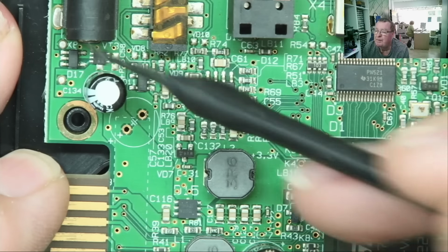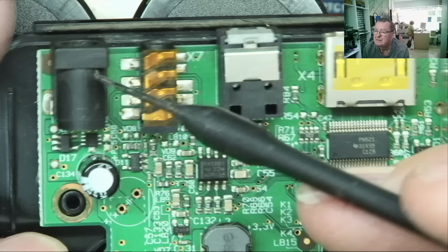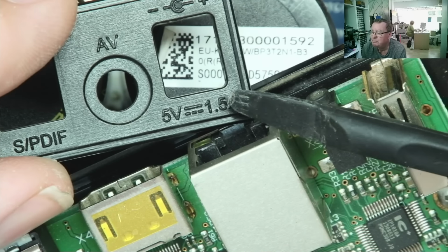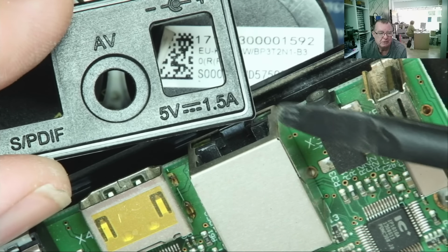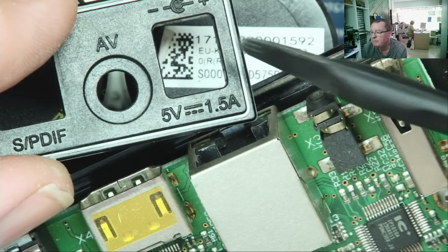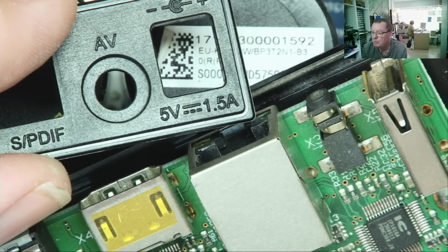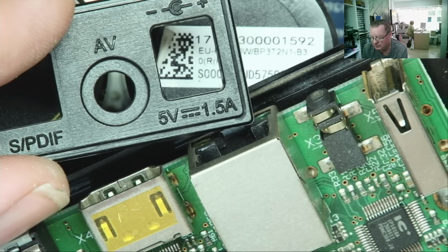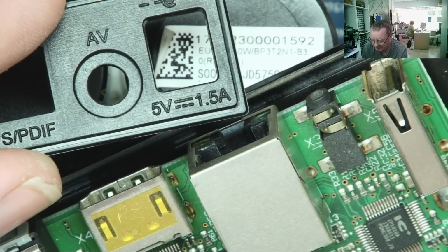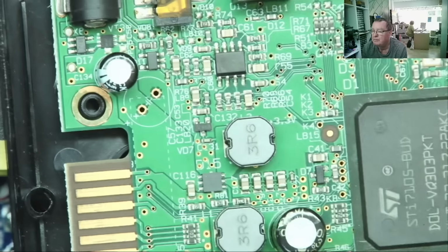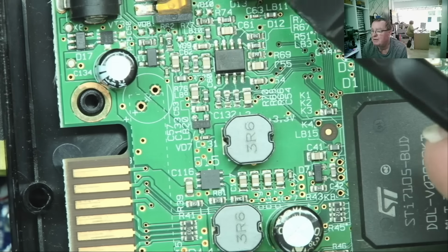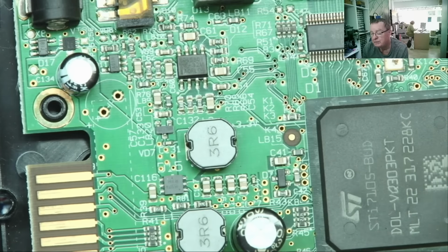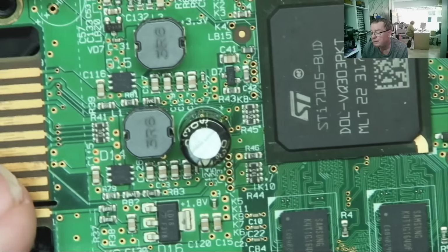The other reason these fail is in cases where the device is externally powered like this. So it says it runs on 5 volts on the back there, for example, but that doesn't seem to matter to a lot of owners who will happily, because they can't find the power supply, plug a 12 volt or a 19 volt power supply into this and then be surprised because it failed. Okay, so those are the most common reasons that these devices fail. And before you change the device, make sure you don't have a shorted output. I mean, you may not. Maybe the device has just got a hole in it. Yeah, they do sometimes just fail.